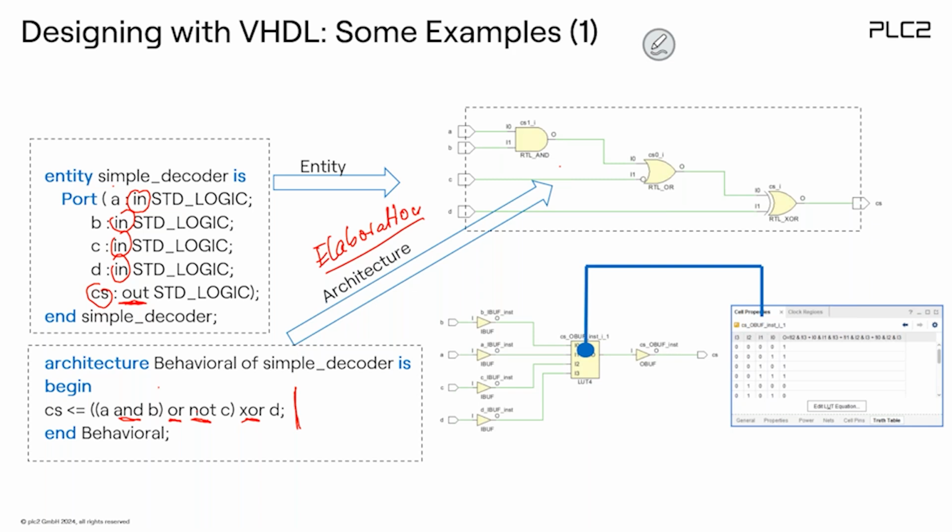You see, that's using generic information, and then you understand, yeah, that's okay. That's my intention. That's exactly what I need. So this step could be used very nicely to check your results, if you like. But then, if you continue and say, well, do for me the implementation now, then you will get this netlist which will be implemented. You will get an input level shifter connected to the pads A, B, C, D, and so on. So these are input level shifters, depending on the type of input, could be CMOS or could be TTL or could be whatever you like.